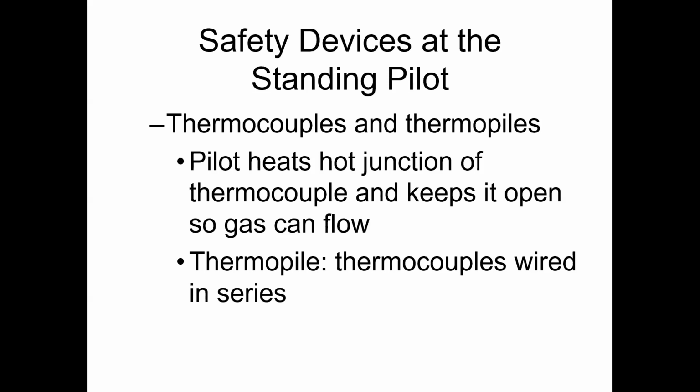What I want you guys to understand is that thermocouples and thermopiles are very much the same thing. A thermopile is a bunch of thermocouples wired in series, right? They can actually generate voltage with that, which is the cool thing about a thermopile. What a thermocouple does is it sits directly in the flame. It's going right there in front of that burner, right in the flame.